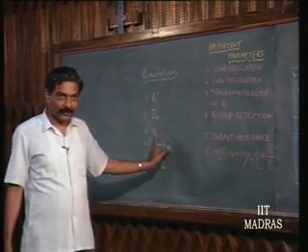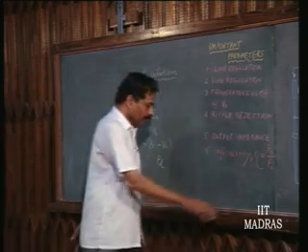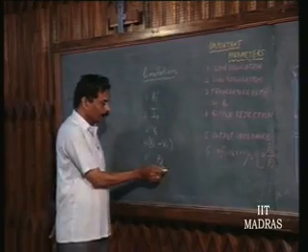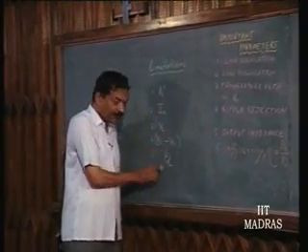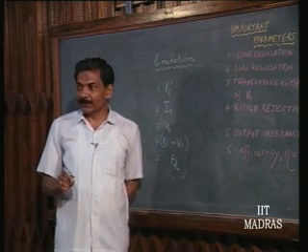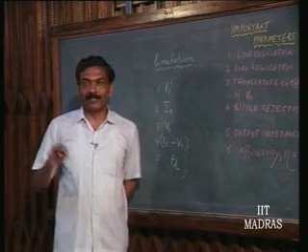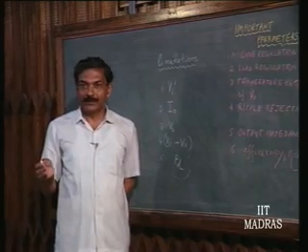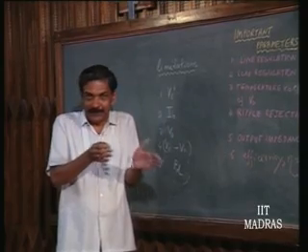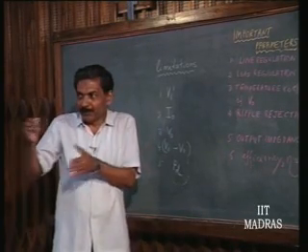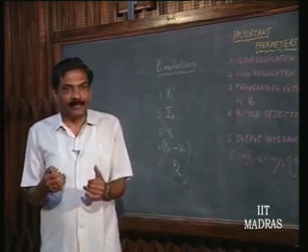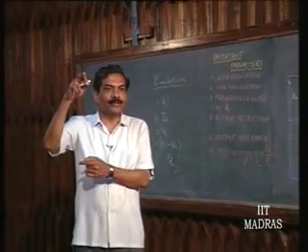Is that clear? So, let us now discuss. First, let us take it this way. We will go this way, because this is finally the most important thing. The voltage regulator is not doing any amplification or anything. It is just being inserted into the power scheme, DC power, so that output DC power is something that we get anyway, with an output voltage which is constant.